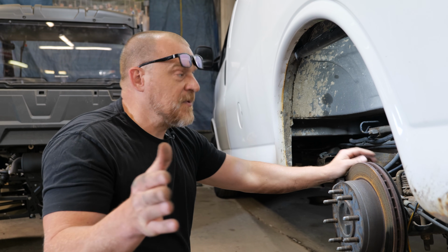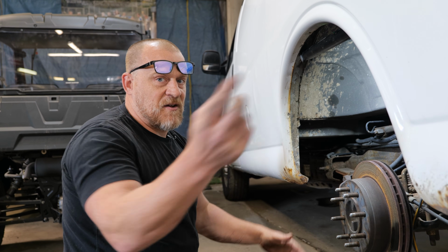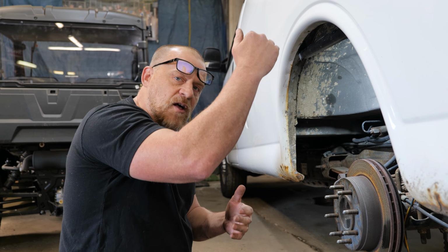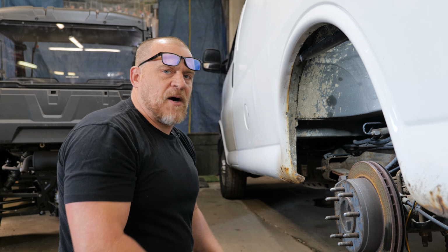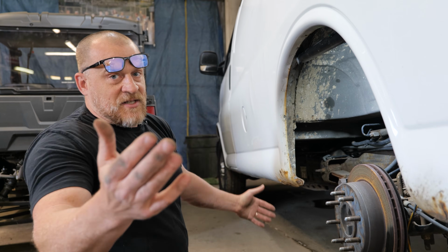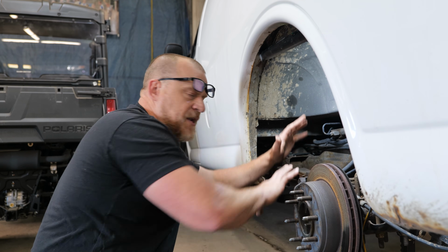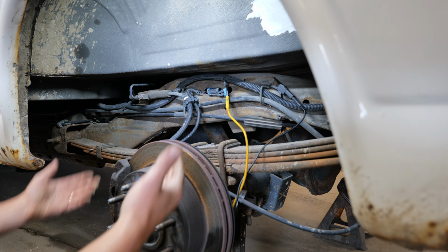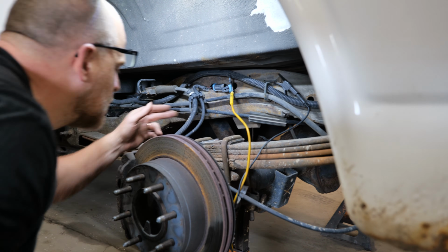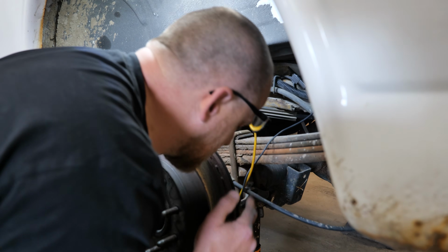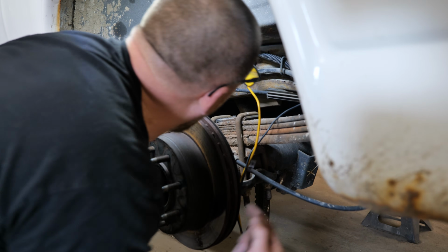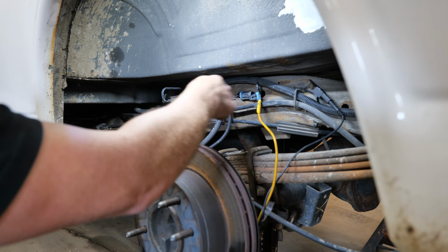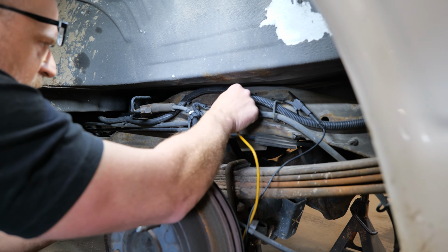Where is our problem? The problem is either a bad ground, which I proved it's not because we plugged it in, got 0 volts. A bad ground's going to have elevated voltage when you have a bias line. Really, just in general. Our problem is right here, Caleb. From here down is where our problem is. This is all new. Is it? The sub harness is not new. There's a connector here. Oh, I thought this sub harness was new. It's not. We're going to focus on the sub harness now.